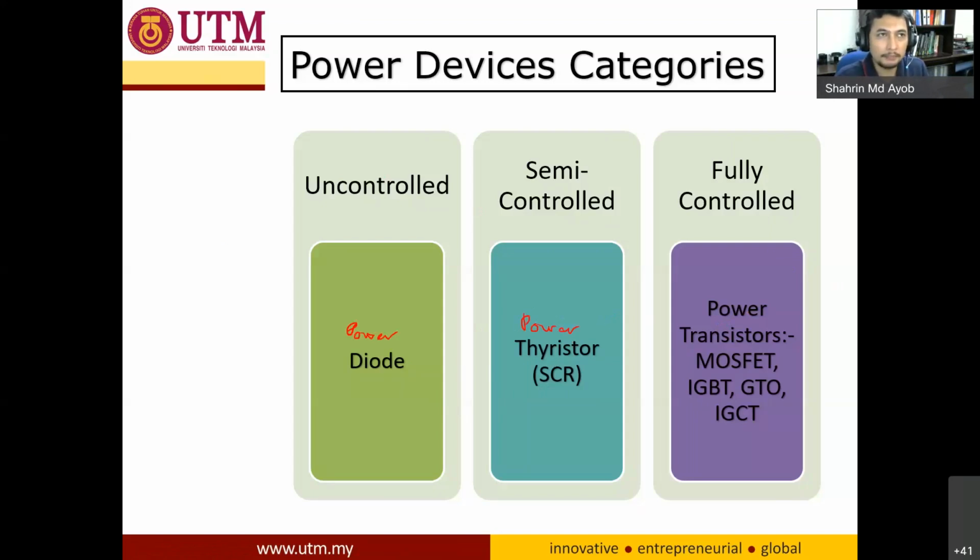In electronics, the voltage is around 5 volts and the current is in milliamperes and so on. But a power circuit is up to 1 kilovolt, and the current can be up to 1 kiloampere. So that is the difference, meaning that the rating of the power diode is not similar to the rating of the electronic diode.